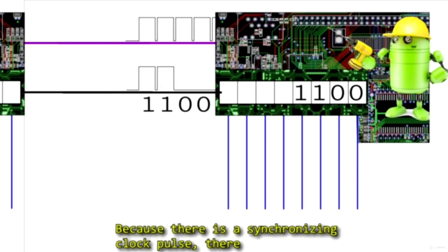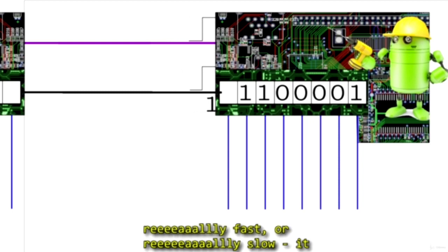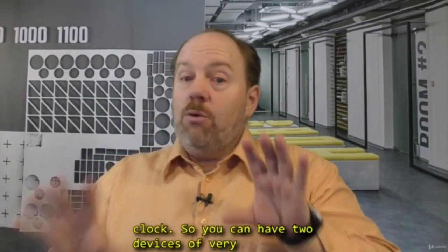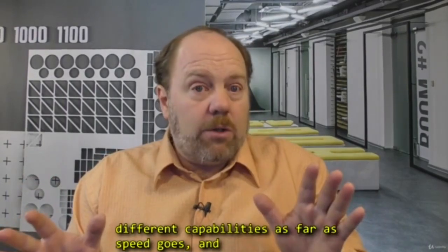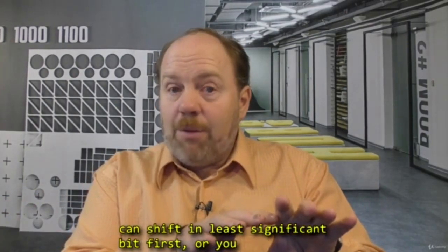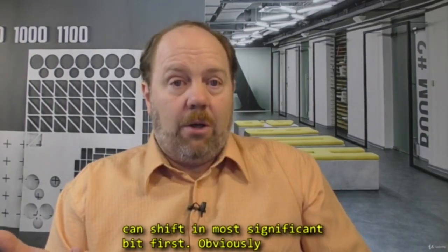Because there is a synchronizing clock pulse, there is a lot of freedom in timing here. You can go really fast or really slow. It doesn't matter because there's a synchronizing clock. So you can have two devices of very different capabilities as far as speed goes, and they can freely communicate with each other. You can shift in least significant bit first, or you can shift in most significant bit first.